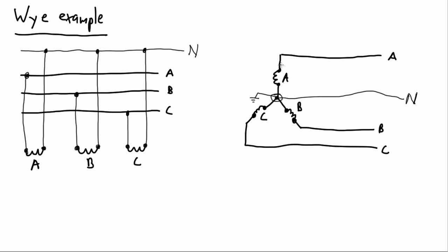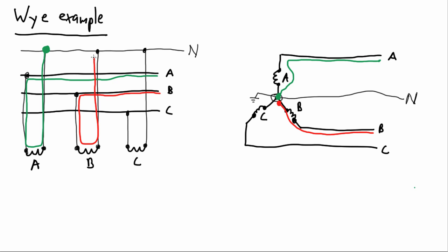So now let's illustrate our flow of connections. We'll start out now on the A line, the line that's bringing in power, and we'll bring it all the way to our neutral connection, that central connection in the Y that we see visually here. How does that look in our 3-line, well now 4-line diagram? We go here, makes the connection to the A inductor, which is then connected to the neutral. The B connection, starting out in our B line, we can show here, and that comes in, crosses the B inductor, and connects to the neutral. So let's follow it here on this other diagram. We start here. It makes the connection to the B inductor, and just like before, we see it gets connected up to the neutral. And now we do the same for C. Once again, following the same path from the incoming power line to the C inductor to the neutral.